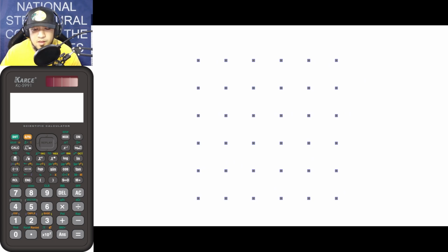Suppose that we do not have any beams, we do not have any bracings, we do not have any slabs. So again, they are individual columns. So suppose that we are to apply a lateral force here. So the only column that would withstand that is just this particular column. It is just it. Okay?